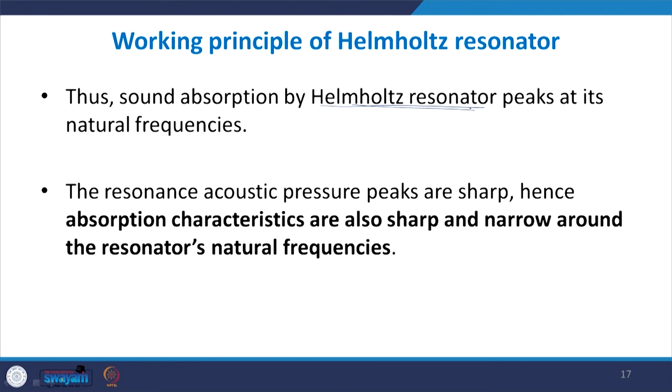So that is why these Helmholtz resonators are very selective. They have a peak at the resonator's natural frequencies. So if we draw the alpha, or the absorption, of this Helmholtz resonator, then wherever the incident sound frequency matches with the actual frequency of the resonator, so if this is the natural frequency of the resonator, it is only there that suddenly the acoustic coupling takes place, and the energy that is incident will then be used to drive the molecules of the resonator.